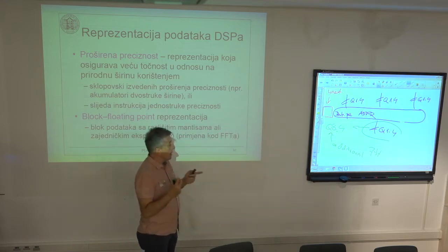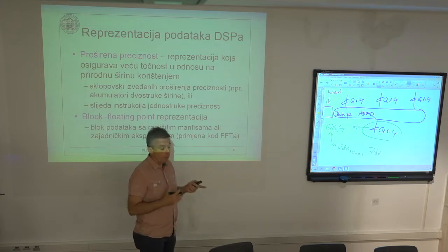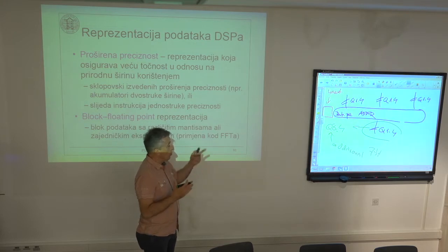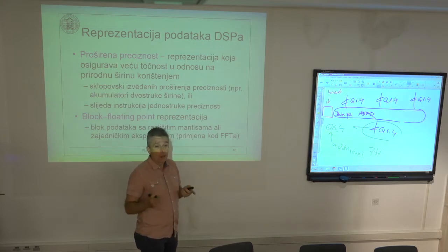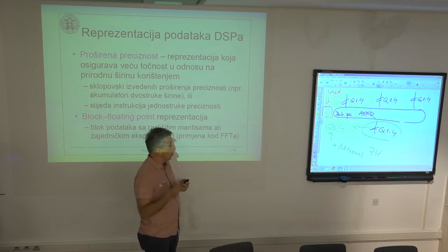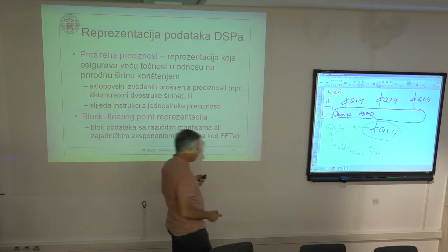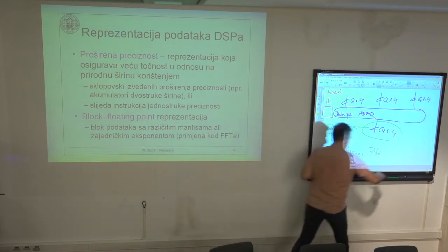How many bits I add to the left side only depends on the goal. So if I want to add 100 values without bothering about the overflow, I must have at least 7 bits to accommodate such 100 products.